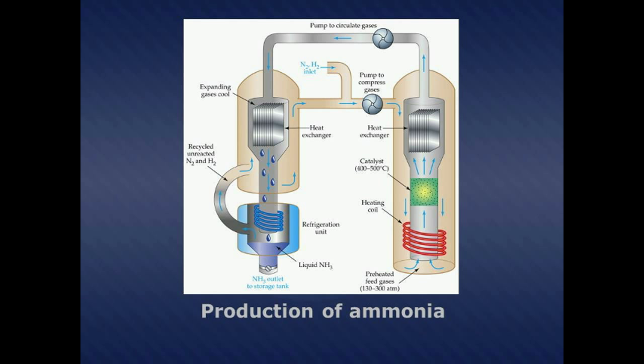Here is an ammonia plant in working conditions. The process carried out in the production of ammonia is Haber's process. Haber invented a large-scale catalytic synthesis of ammonia from elemental hydrogen and nitrogen gas, reactants which are abundant and inexpensive. By using high temperature around 500 degrees C, high pressure approximately 150 to 200 atm, and an iron catalyst, the Haber process combines nitrogen from the air with hydrogen derived mainly from natural gas into ammonia.